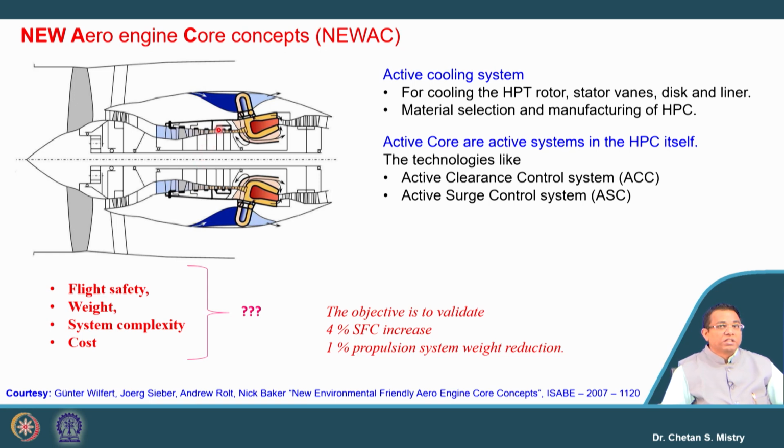Okay, in this if we look at carefully, this intercooler is being placed in this region, and it is with a specific reason, where by using this intercooling, we will be able to cool down the air which enters inside the combustion chamber, and by doing so we will be moving towards the lean combustion. That will be helping in terms of reduction of NOx as well as the specific fuel consumption.